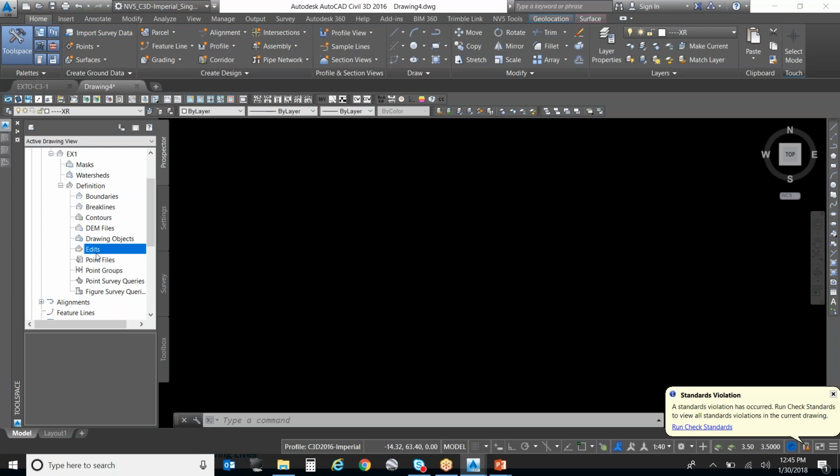And especially keep that in mind if they're using GPS, right? The big thing with GPS is you need to cook the point a little bit, all right? You're getting signal from satellites, right? So you need a little bit of time for all that triangulation to happen, which means the surveyors have to cook the point for typically, 10 seconds? 3 seconds. So on a busy intersection, they don't want to be there any longer than they need to. So they're going to click the button and run, right? So again, be aware of where your data is coming from, what collection method is being used, and what kind of accuracy you have introduced into your surface.